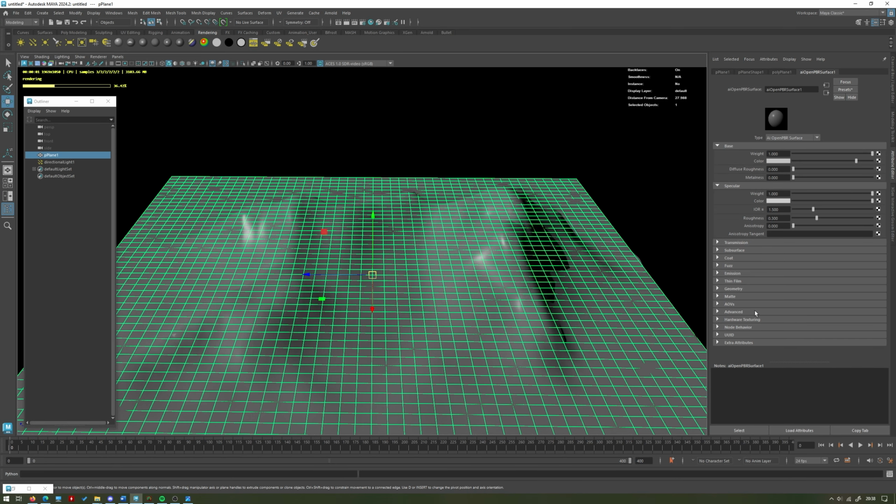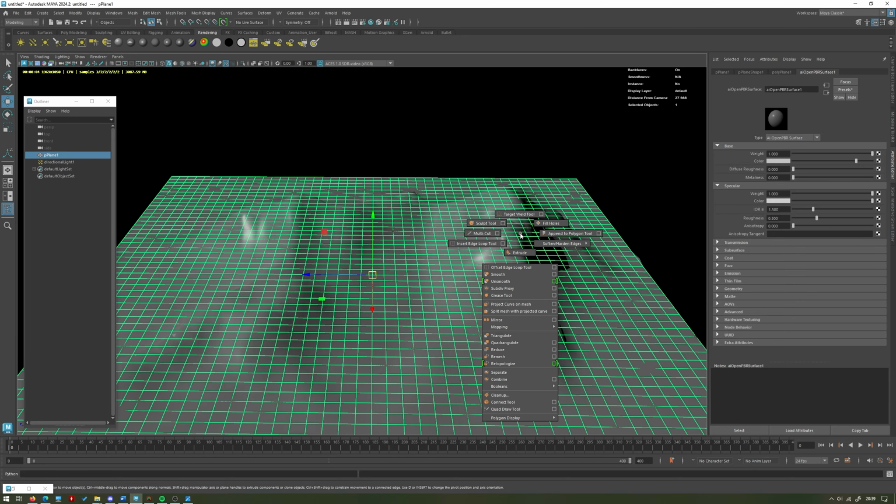If you really, really do need to crank this up, be warned, it is going to slow down the render times quite a lot, both how long it takes for the render to start and actually render. You can see right now I'm at 4 seconds per frame just in the viewport here. So if you're going to have to subdivide this, I would not just go to smooth. I would do this at render time.